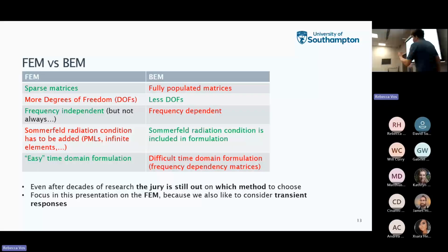Of course, with the BEM, you have certain nice things that are not in the finite element method, like, for example, the radiation conditions, the Sommerfeld radiation conditions, so the conditions where you have an exterior problem in which the sound is basically radiating to infinity. You can basically see it as standing in the desert and screaming.